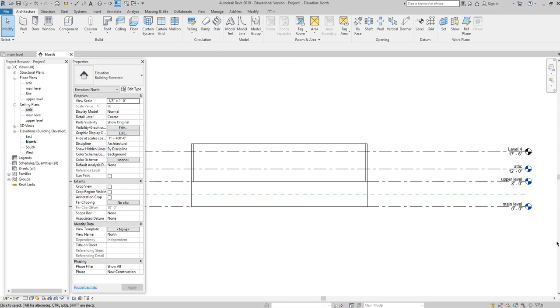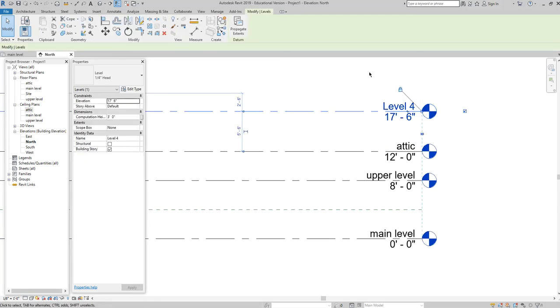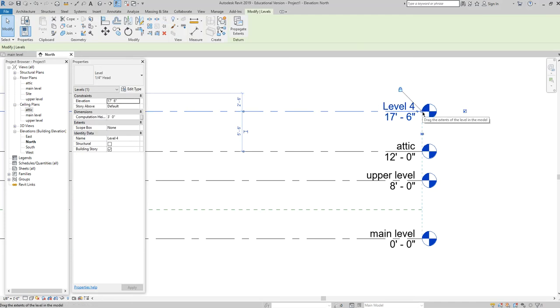So this is how you're going to create your level markers. Just a couple other things and we'll finish up here. You can click on your level marker here, and there's a little, what we call an elbow. So if one of these is so very close to the next that they're overlapping, right, I could use my little elbow and I could move it so that text doesn't overlap itself, okay? Pretty helpful. And if I want to make it straight again, I can do that, okay? I've got these little grips at the end here that move it back and forth.